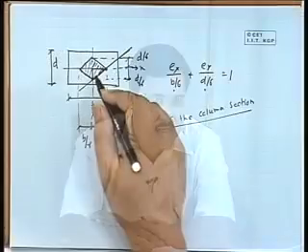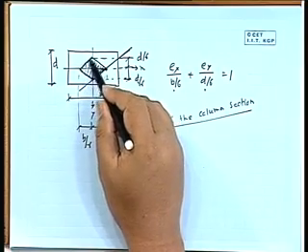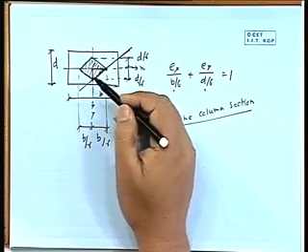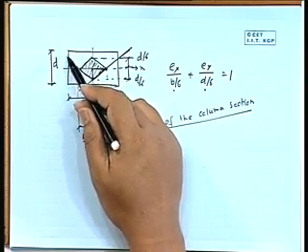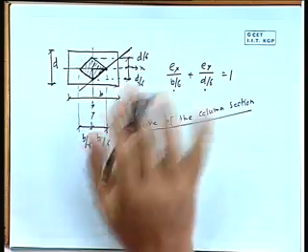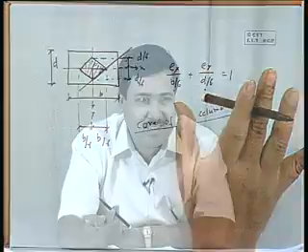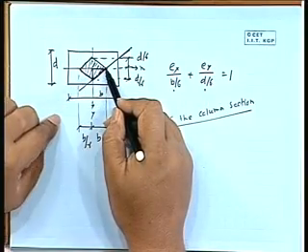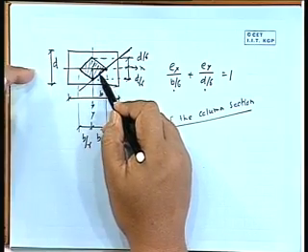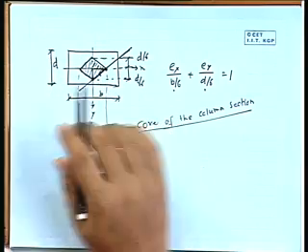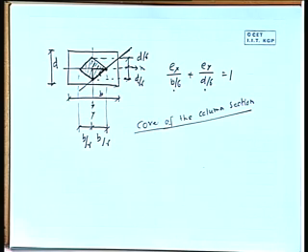right. This is the boundary. If the load is at any point on the boundary, means one of the corner point or one of the edge will have a stress equal to 0, right. Say if it is here, the edge will be 0, if it is here, this edge will be 0, if it is here, this corner will have 0. So it will be a limiting case.